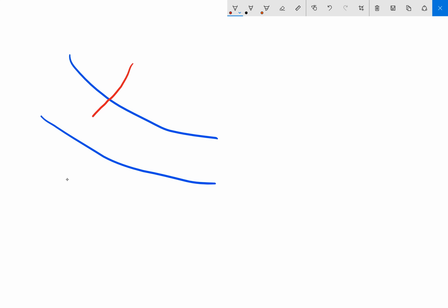So we want them to try to intersect our flow lines as best as possible. Now, if I had an equipotential line over here, you can see that this element that's formed looks more rectangular than anything, so that's not going to work. We need our elements to be approximately square. Now, again, we're not looking for perfection here, where this distance across and this distance up are about the same.